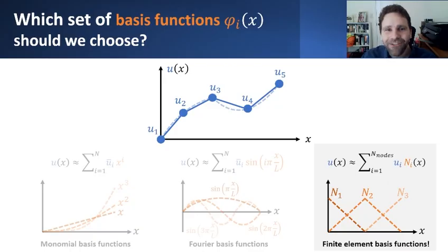In general, though, they aren't always exactly smooth, as is evident from this particular example, where if I wanted to represent this somewhat general function using a low-order finite element set of basis functions, which basically give me piecewise linear interpolation of these discrete values, u1 through u5, corresponding to nothing more than the actual displacements at those specific locations, then you'll notice, even though things are linear over these individual subdomains, or the elements as it were, nonetheless you have these discontinuities or kinks in the representation of the solution field as you traverse from one segment to the next.